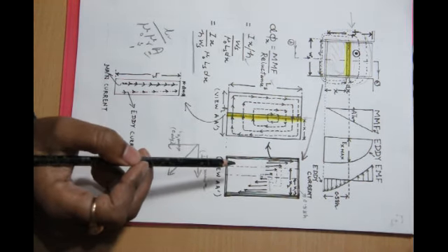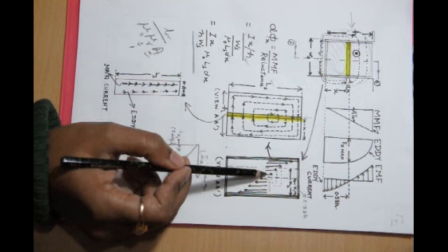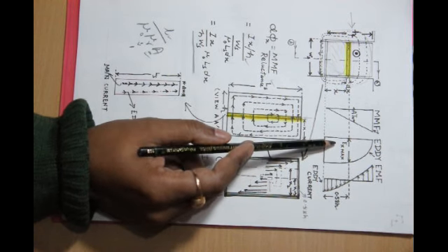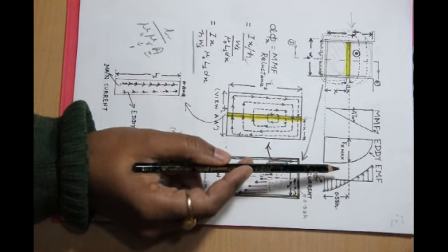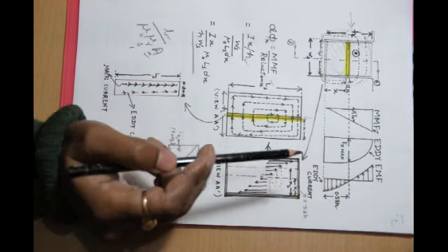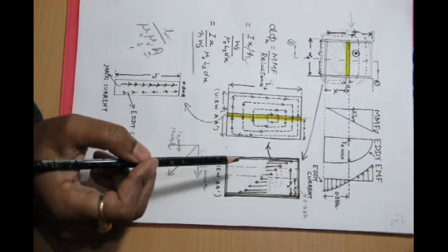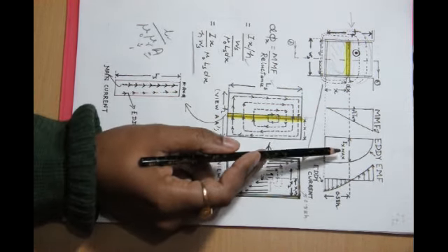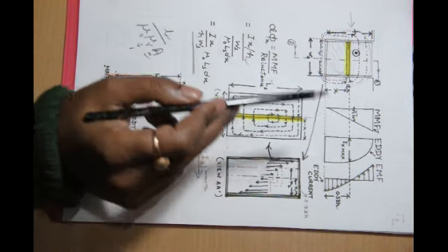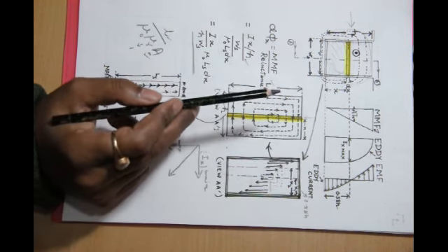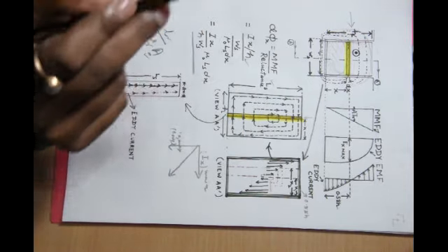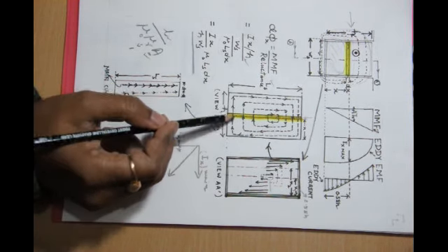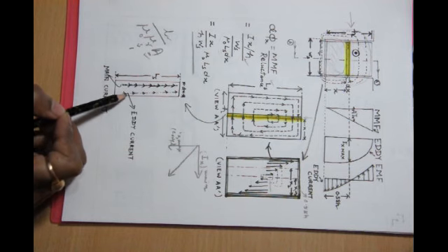So these eddy currents are in phase with Ex max minus Ex max average, because that difference in EMF divided by the resistance establishes the current. But Ex max minus Ex max average is in quadrature with the flux, and the flux is proportional to the main current. In other words, we can say that for each individual element chosen, the eddy current and the main current are in quadrature.